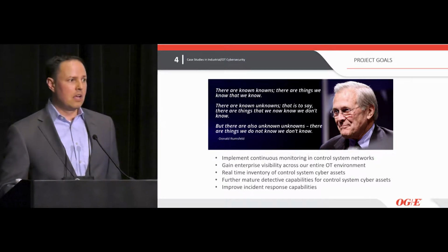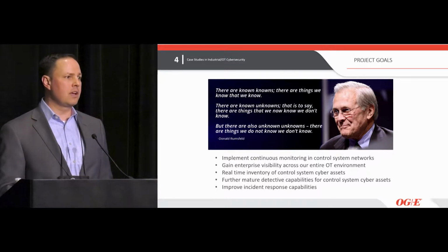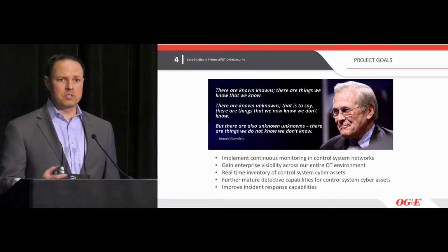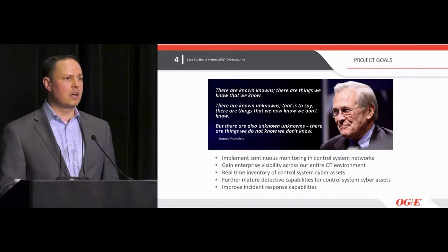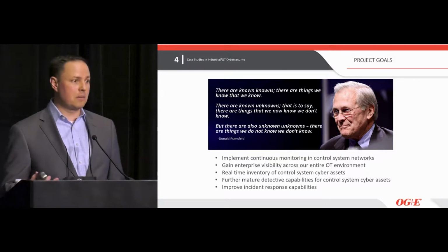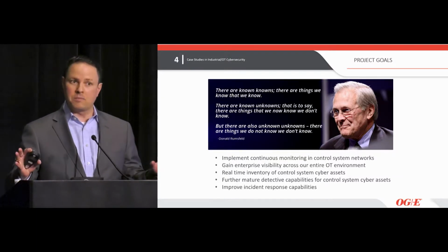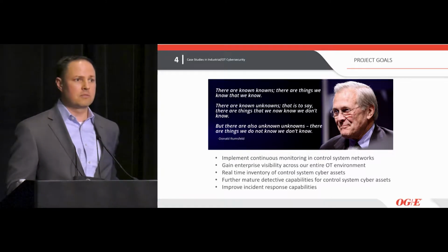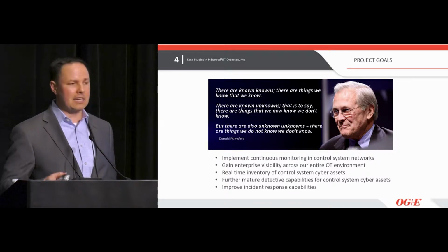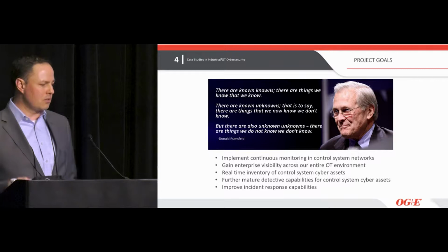In my experience, the security controls that are often layered in are things that I don't even know if they meet the bar of table stakes anymore. We throw antivirus onto a control system and we say we're good, and we all just sort of wink and nod, knowing that the first thing we do after we install that is exclude the program directories where all the control system stuff works, so that we don't mess up operations, right? So, hey, we've got something we can check a box on. We've got a detective control of something, but I'm not sure of the efficacy there, right? And we can talk about role-based access controls and other things, but those are not always detective.